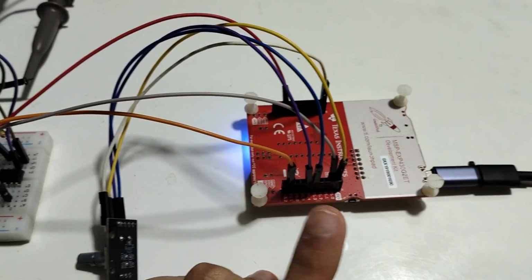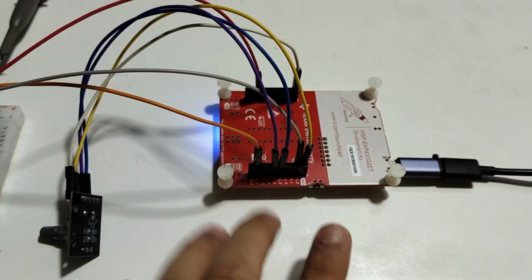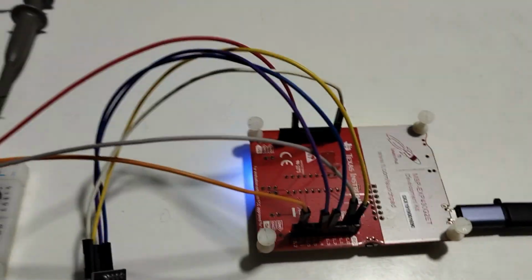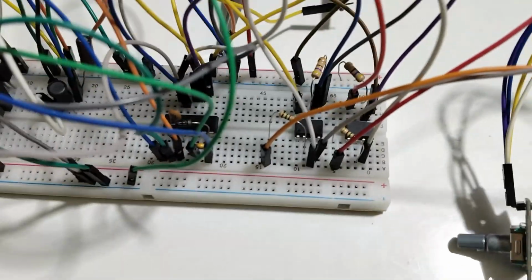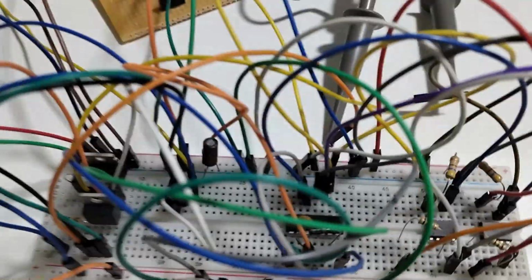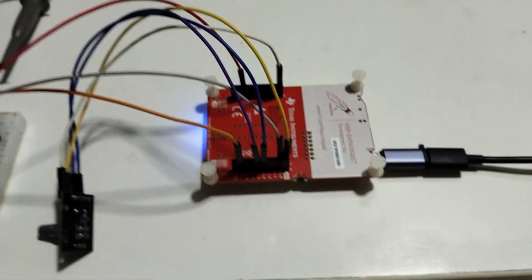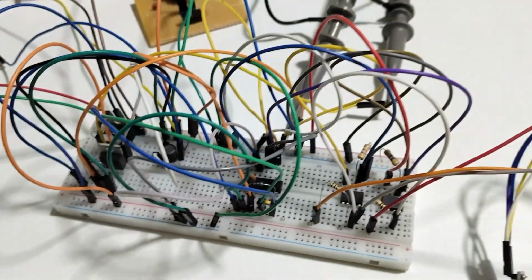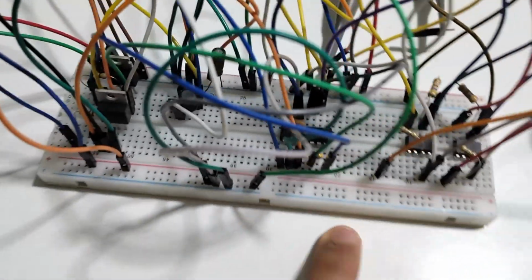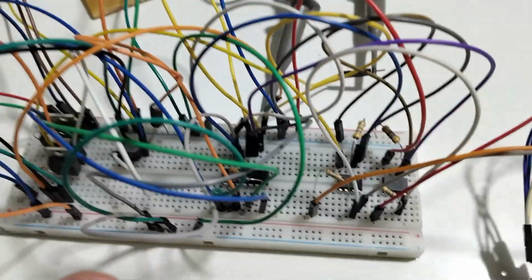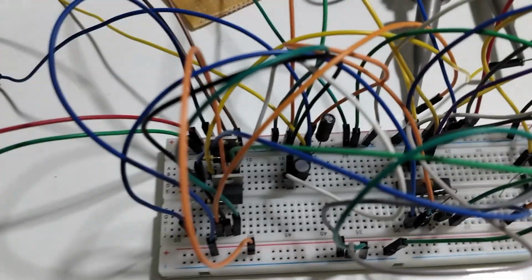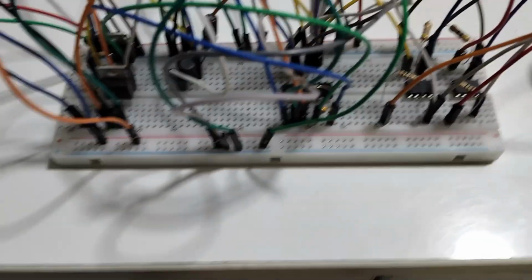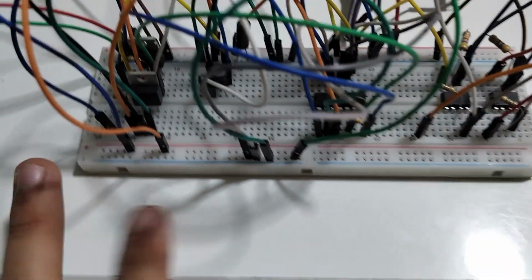And another thing is, of course, digital is good. If any error is there, you can always just debug it. If you try to do it in analog, that's good too, but you would have to mess around with some RC values to adjust all of that. But the MSP is good, and the power electronic circuit worked out fine. And if you lay this out properly, maybe this driver on a perf board or on a PCB, we can reduce these parasitics. Of course these breadboards do have the inductance and all of that, but just as a POC it's good enough that we can see the bucking action happening.